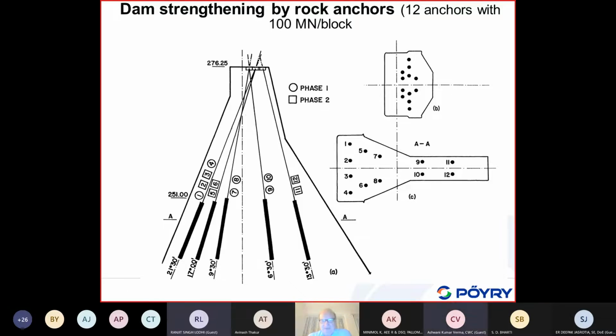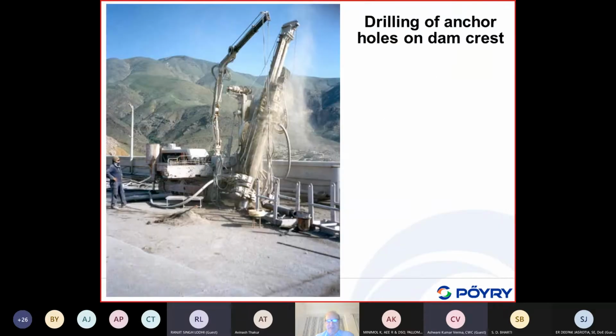And of course, that increases the shear resistance of a fractured lift joint. So that was what was done in this case to increase the shear resistance of this crack. So for this work, a lot of drilling work was being done. The repair costs were about $20 or $25 million, which were done then in 1990 and 1991.